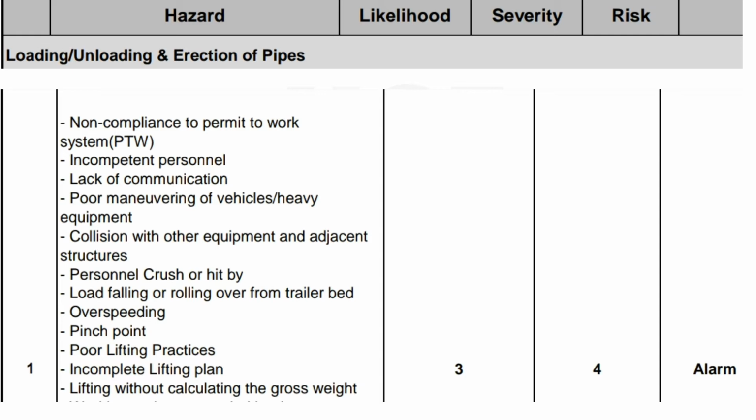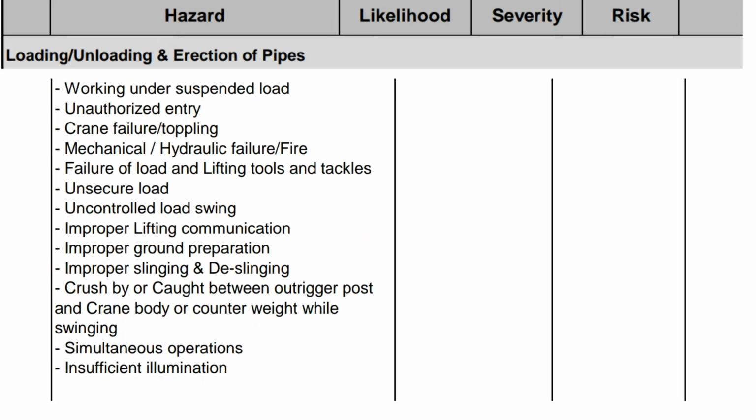Overspeeding. Pinch point. Poor lifting practices. Incomplete lifting plan. Lifting without calculating the gross weight. Working under suspended load. Unauthorized entry. Crane failure, toppling, mechanical and hydraulic failure. Fire. Failure of load and lifting tools and tackles. Unsecured load. Uncontrolled load swing. Improper lifting communication. Improper ground preparation.